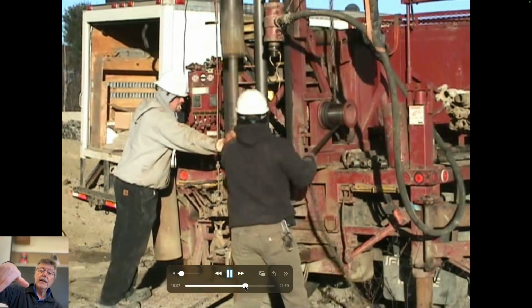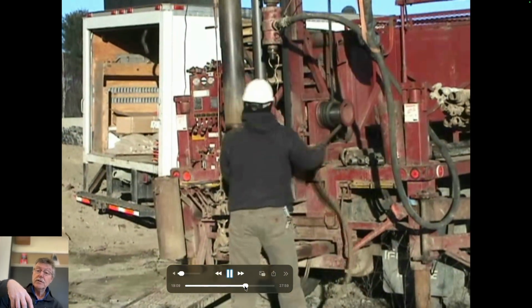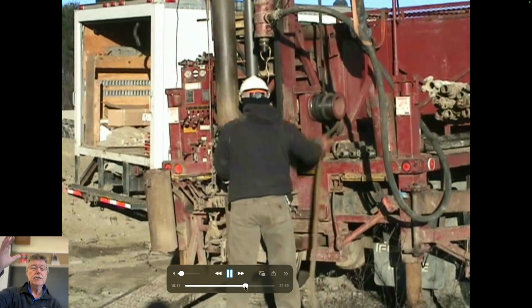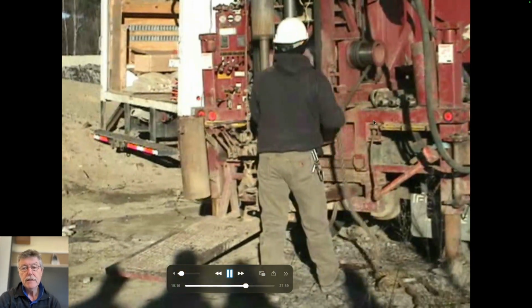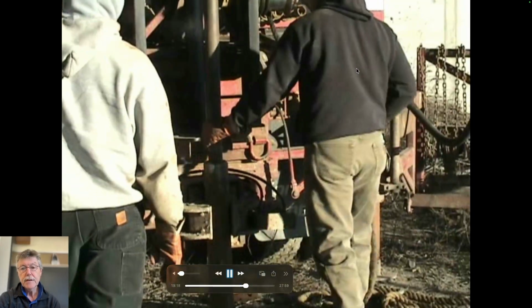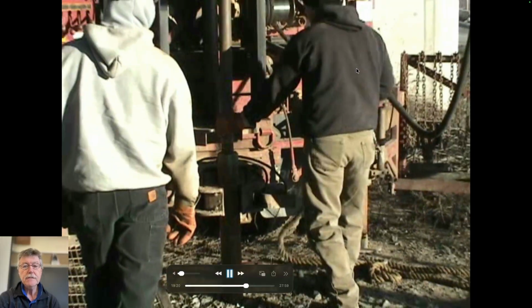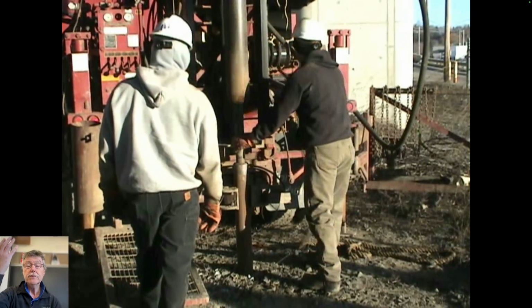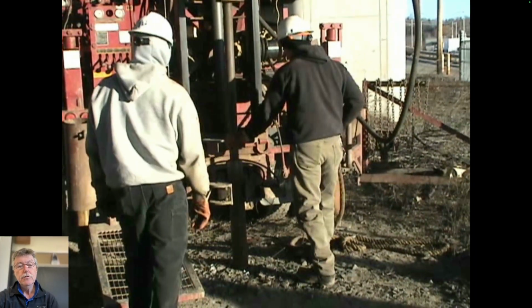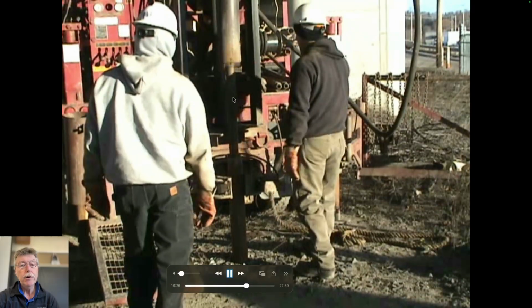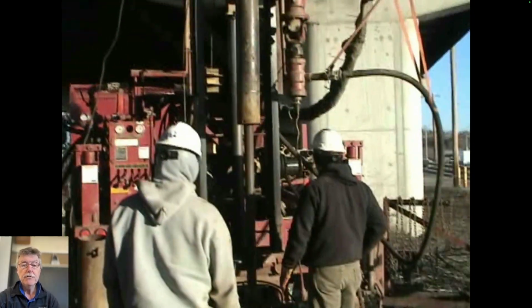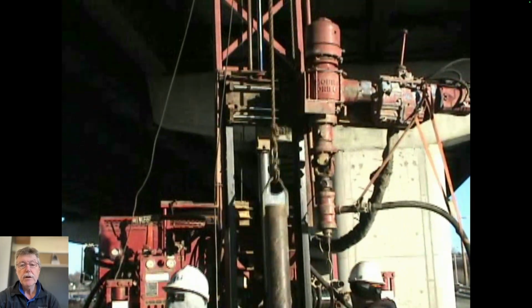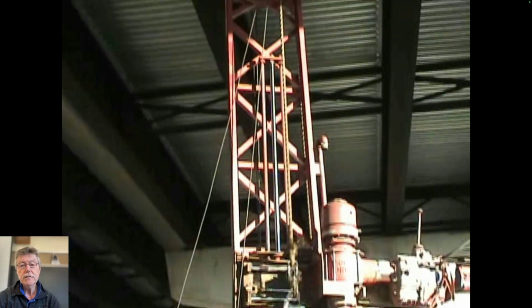So then this hammer is put on top of what's in the hole and then lifted a certain amount, has a certain weight. You lift it by just tightening the capstan here. As soon as it gets tightened, it lifts, and then you take it up to the top of its stroke and drop it down. You dutifully count how many blows it takes to go 6 inches, then a foot, then 18 inches, and record it. And then once it's gone the full 18 inches,